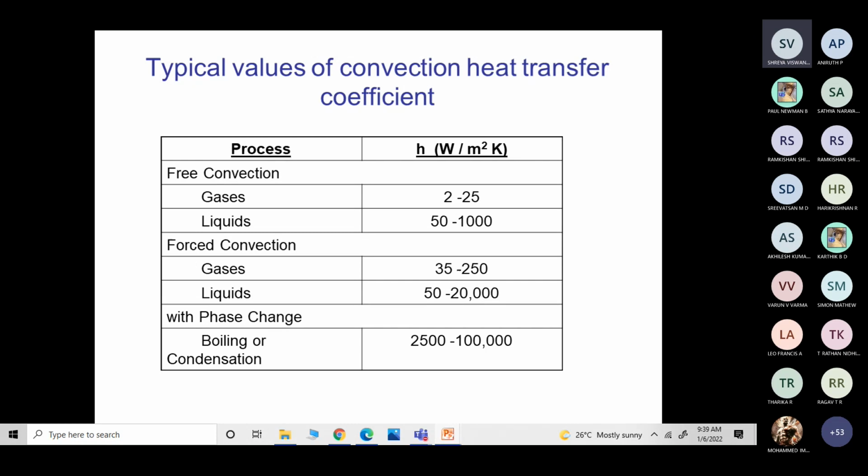That's why, especially for cooling purposes, in nuclear reactors or in steam power plants, we use hot liquids, not hot gases, because the manner in which the heat is transferred from the fluid to the turbine material, for example hot steam to the turbine blades, is much higher compared to when we use some other gases, inert gases. Steam possesses a higher convective heat transfer coefficient compared to other gases. So that's why steam is used often. Steam turbines are used for power production.